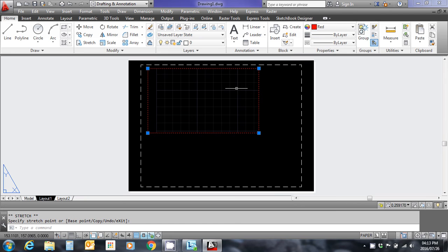The viewport, as I said, is a window that we have into the model space environment. It has certain properties. One of them is that you can choose to either have it locked or unlocked. If the viewport is locked, I'm able to interact with the model space environment through my viewport, but I'm not going to be able to make any changes to the scale by using the dynamic pan function, or by shifting the drawing space around behind the window.